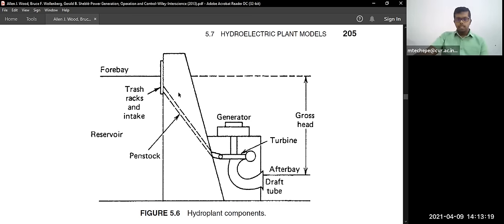So in that case, what they will do is simply install one surge tank over here. What the surge tank will do is, say for example, water is flowing in this direction, so automatically the pressure will be increasing. Now there will be one tank here, which is also connected to this penstock. So automatically the water level in the tank will rise, and automatically the pressure inside the penstock will decrease. So that it can safeguard your turbine also. The turbine also will be safeguarded.